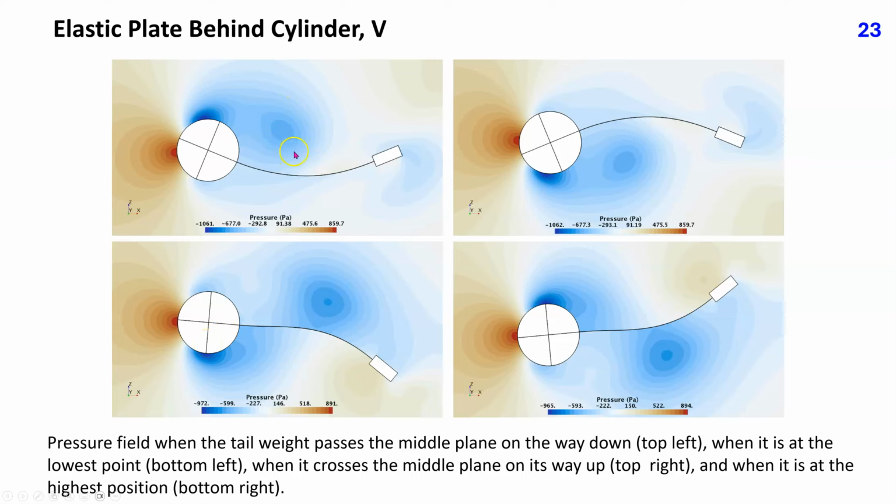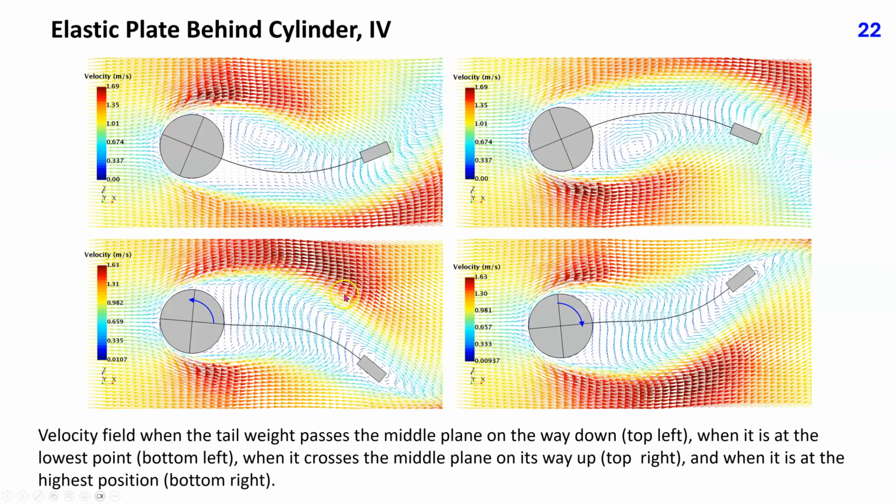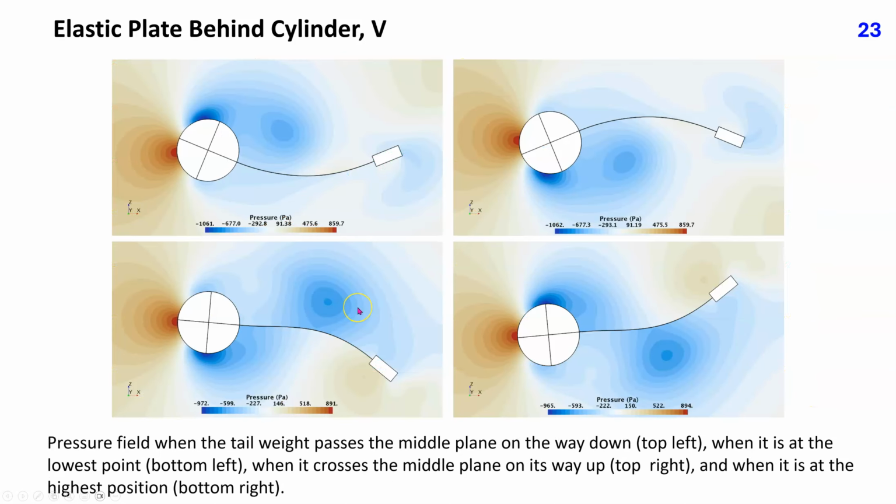This low pressure indicates the position of a vortex, but there is no vortex at this location, as one might expect looking at this plot. However, the unsteady streamlines have a very strong curvature here, as we can see in the vector plot. The interpretation of unsteady pressure fields around moving bodies is more difficult than in the case of steady-state flows.